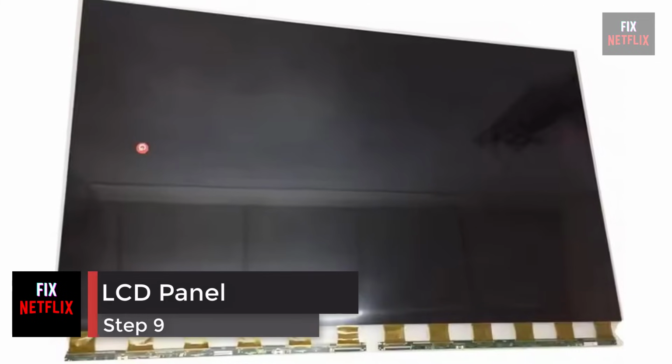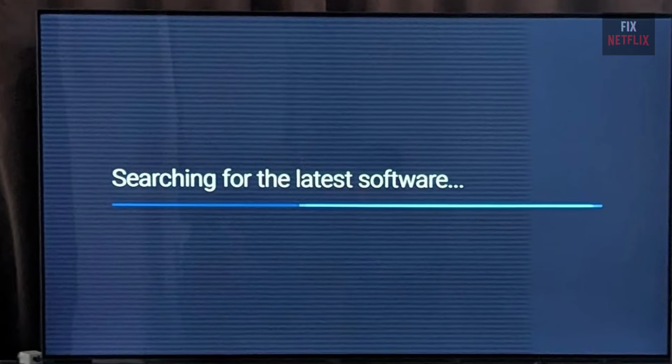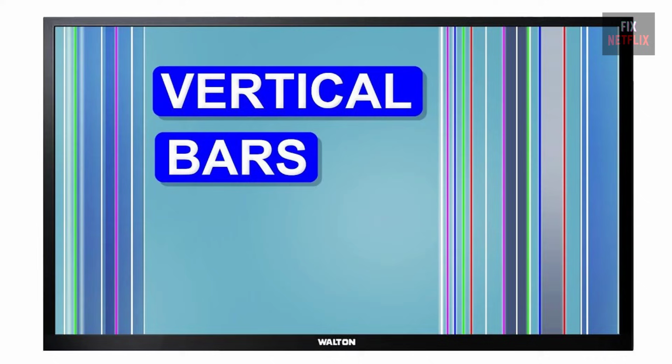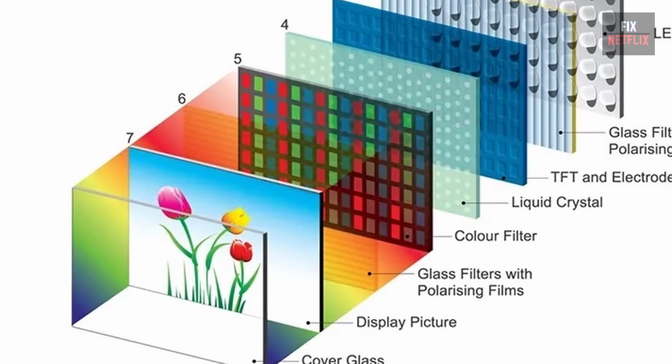Step 9. LCD panel. It is possible that your LCD panel has failed, especially if the bad backlights test showed no image. A common sign of panel failure is single horizontal or vertical lines in the image on the screen. Many panel failures can be traced to physical abuse. Further, the construction of the panels with chips embedded in flex plastic or attached to glass makes them vulnerable to unrepairable failures in those devices that surround the panel periphery.